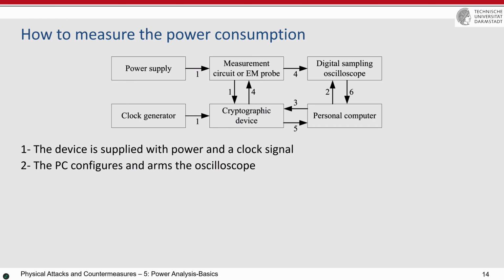Say, okay, at the same time, it should also start measuring or start collecting the data, because the oscilloscope is always measuring, always turning the analog data to digital data, but it's not saving into the sampling memory. Then you should say to the oscilloscope, okay, now start. But you should also configure the oscilloscope and say, this is my trigger signal. Be ready: if one low to high signal comes to the trigger signal, then I start measuring or saving. And this process of watching this trigger signal is called arming the oscilloscope.